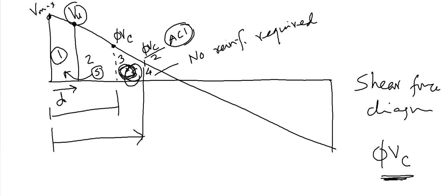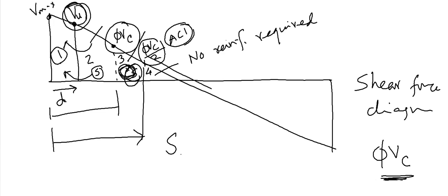Now how to calculate spacing? That table will give you the summary. Before using that table, make sure you draw this shear force diagram. Draw the shear force diagram, locate the design shear force, locate φVc, locate φVc by 2, and calculate the distance. Then calculate the required spacing here, calculate the required spacing here, and whatever is here, copy and paste here. And based on the required spacing and the maximum allowable, choose a convenient round number.